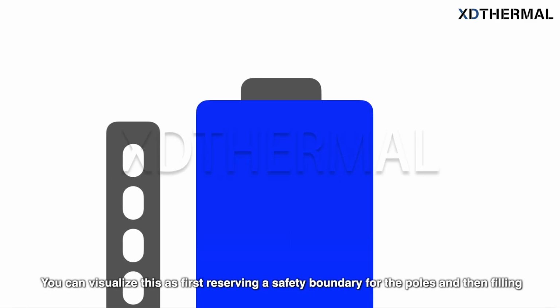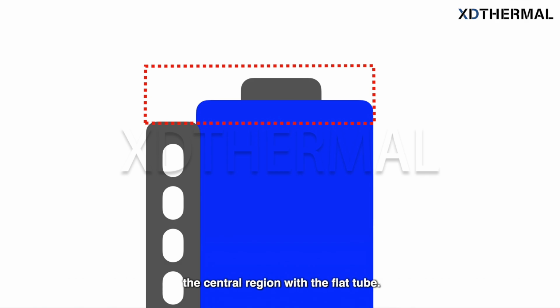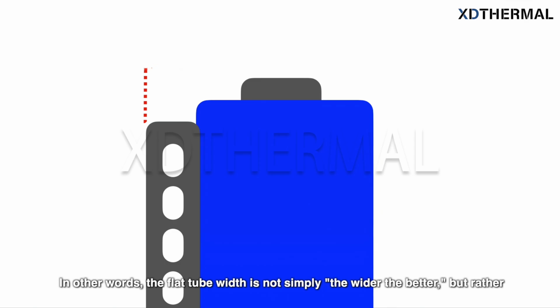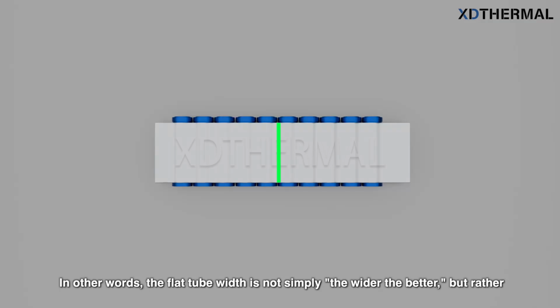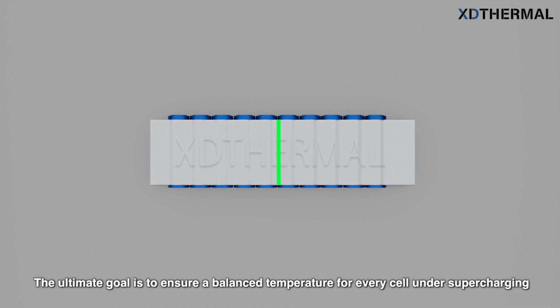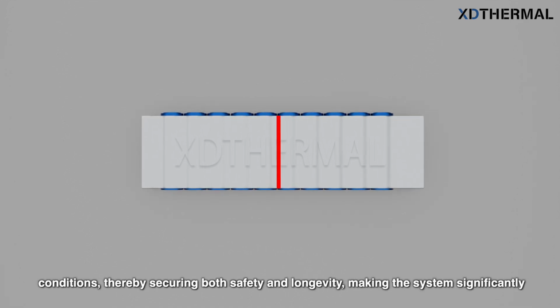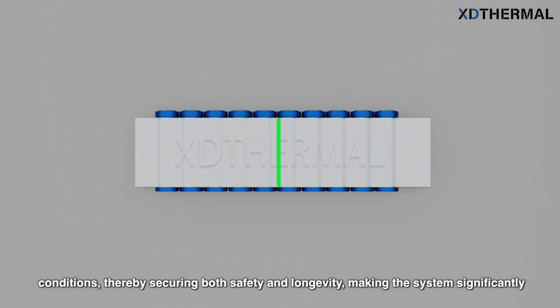You can visualize this as first reserving a safety boundary for the poles and then filling the central region with the flat tube. In other words, the flat tube width is not simply the wider the better, but rather as wide as possible within safe limits. The ultimate goal is to ensure a balanced temperature for every cell under supercharging conditions, thereby securing both safety and longevity, making the system significantly more reliable.